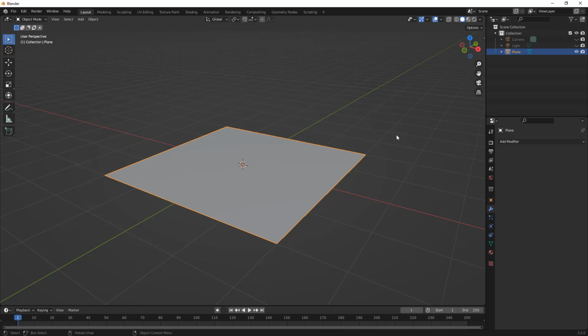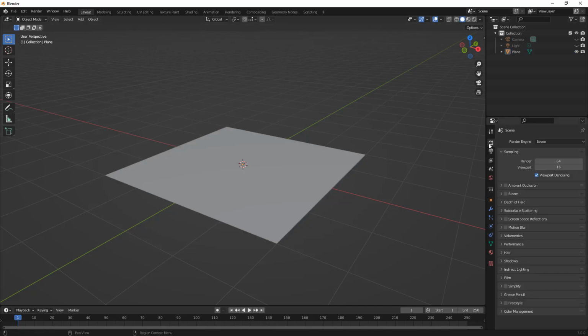Another thing to note is that the units in all the default Blender new designs are going to be in meters. We can modify some of these options by coming over to the left-hand side and looking at some of the properties. It is important to note that the menus that we see on the right-hand side are going to be contextual. So right now, you'll see that we have our plane selected. If we left-click, then we can go into some of our other properties and we can find the location of our units. So anytime we hover the cursor over one of these, it'll display the name.